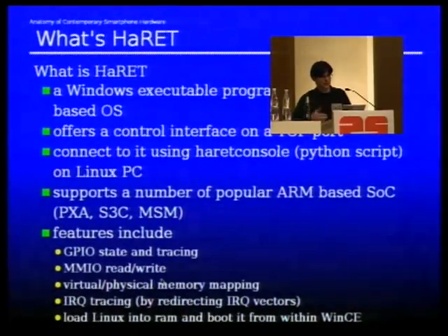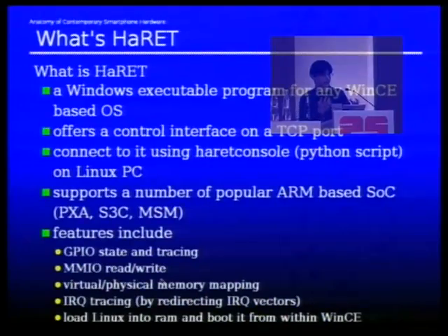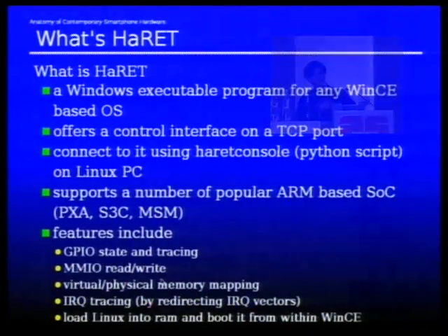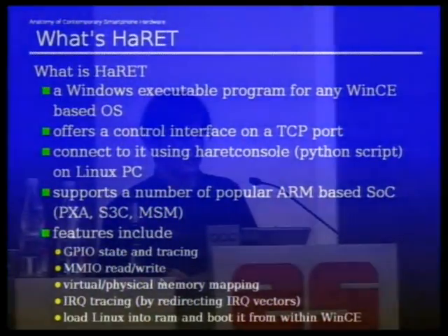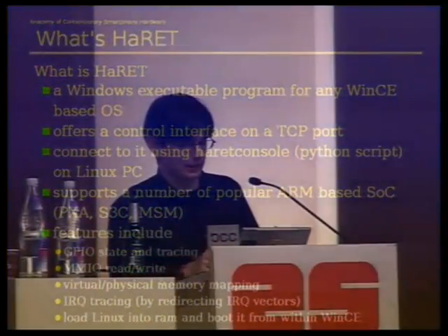And you remove the ones that are noisy, and then you start pressing keys or sliding the slider, switching on and off your backlight, switching on and off your Wi-Fi, switching on and off your GPS. And you try to see what kind of GPIO pins or interrupts happen, or what happens on the device when some kind of external event happens. So you can learn more about how the device works. It supports a number of different ARM-based systems on a chip.